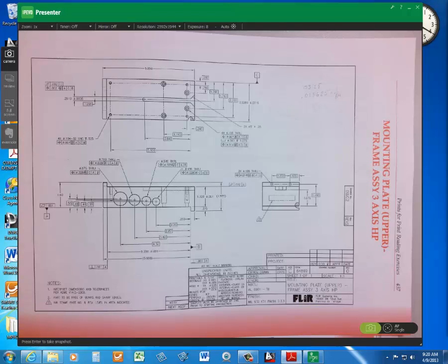Okay, and that's going to touch the sides of the screw. Some screws have a long shank on them, no threads, that is of a higher precision and controlled diameter, and that may be important for assembly of this part and actually touches the sides of the screw shank, okay, and holds it in position. So apparently, that's pretty tight control for a screw hole position.